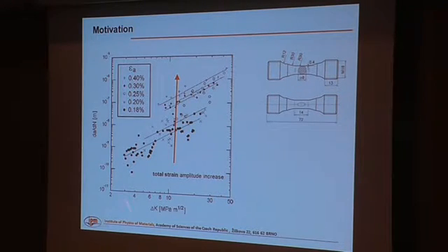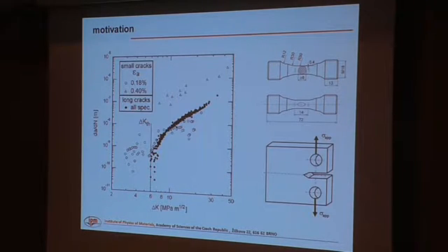And when we plot the diagram of fatigue crack growth rate against the stress intensity factor range, we found that each applied strain has its own fatigue crack growth rate curve, so it's impossible to predict fatigue crack propagation even for only different loading conditions, which is not really useful.